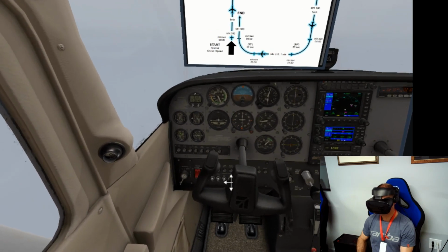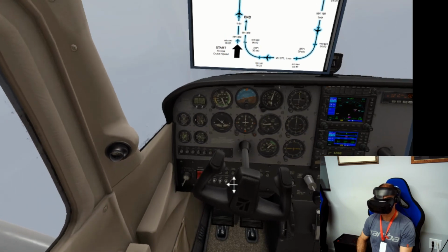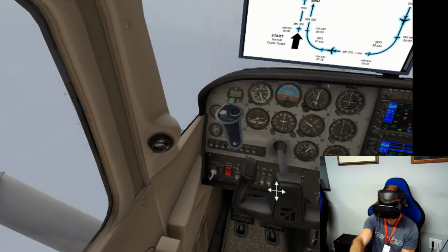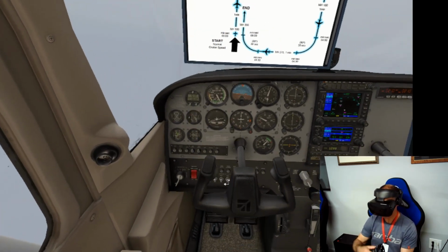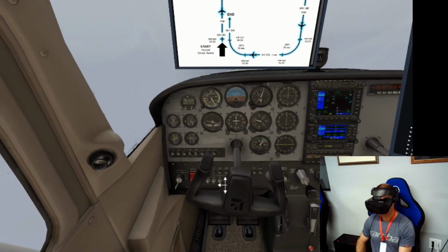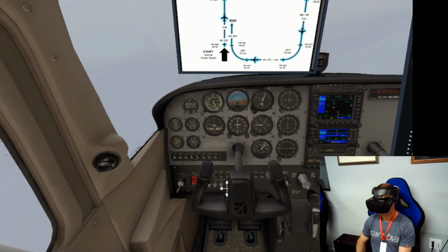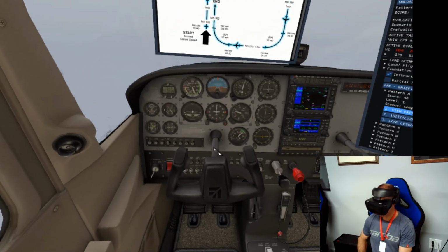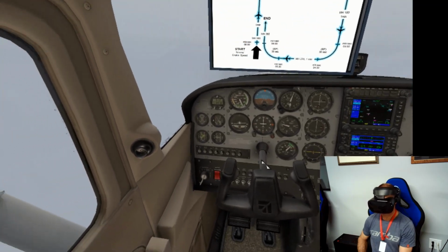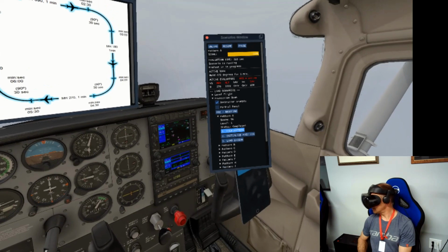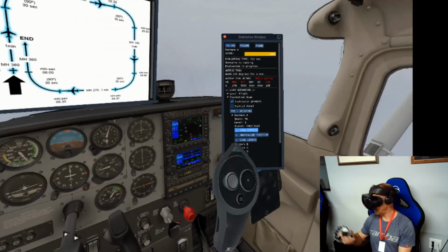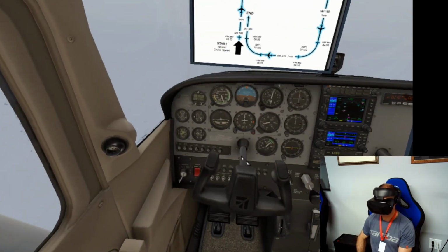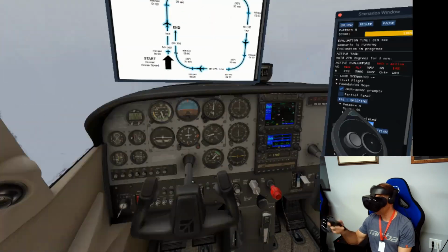Now, start a right turn to 270 degrees for 30 seconds. And let's restart the timer now. Now, hold this heading of 270 degrees for 1 minute. Check your heading. Oh, I got off. Turn right to a heading of 270. Oh, I still have 100%. Done pretty good of maintaining my heading. Still have my active heading, altitude, and speed, and it's telling me what my current active task is, 270 for 1 minute.